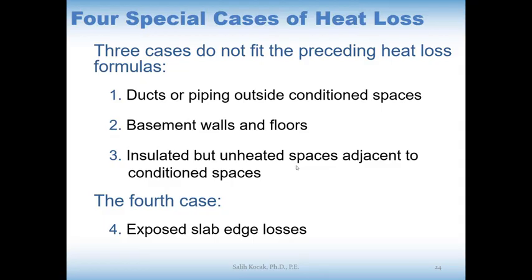When I am doing these calculations, you are going to see what it means exactly, but just make a note somewhere for the exposed slab edge losses. We can still use the U times A times TD equation, which is the conducted heat equation, but allowing an extra 1 square foot of area for each linear foot of slab edge.